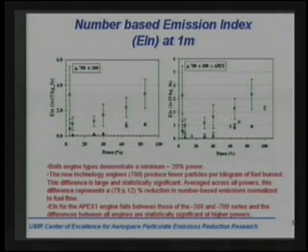So, emission indices. We're looking then at, in this case, the number of particles per kilogram of fuel burned here. Okay, so we're normalizing to the fuel flow. And what we see is that for both engine types, we have a minimum around 20% power in the relationship between the number-based emission index and power. The new technology, 700 engine, produces significantly fewer particles per kilogram of fuel burned.